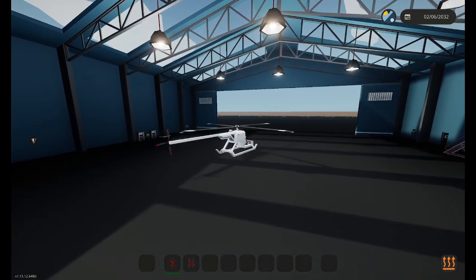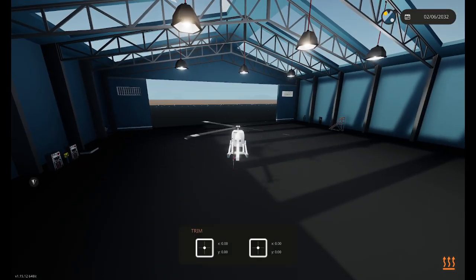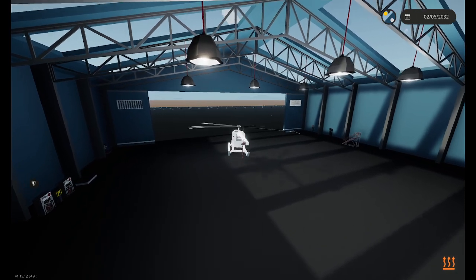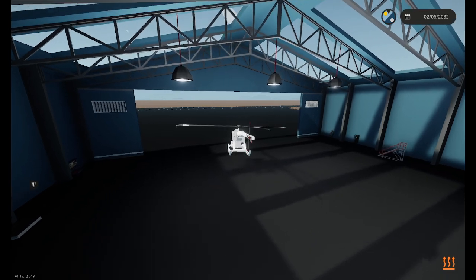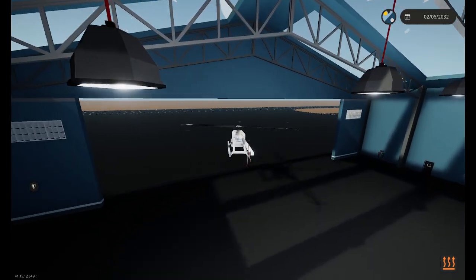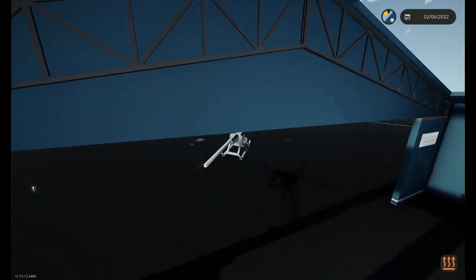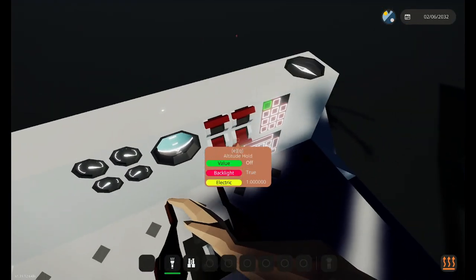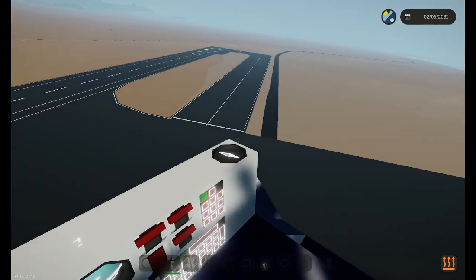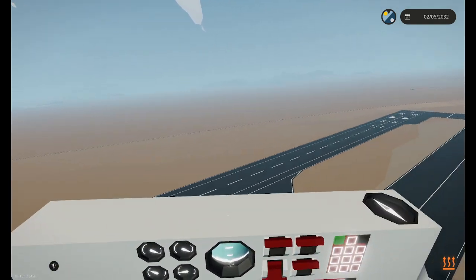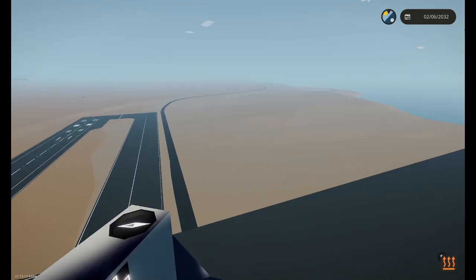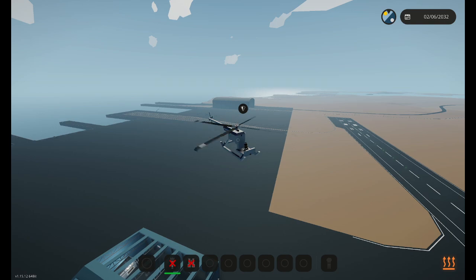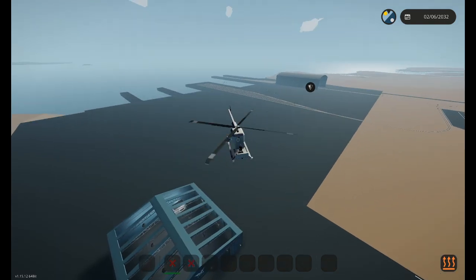One other thing to note is you have trim values for helicopters. A lot of people use them. If you want to trim your helicopter with those, take a note of your trim values for if they're in yaw or if they're in pitch, particularly yaw, and you'll want to put those into a function block where you do x plus whatever your trim value is. If you do this, the trim will continue to work when the autopilot is active. Otherwise, the autopilot might end up fighting your natural rotation.